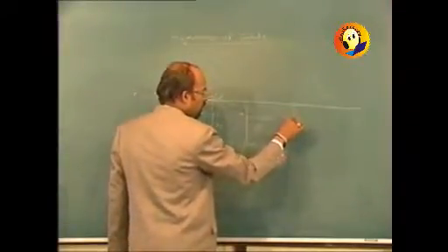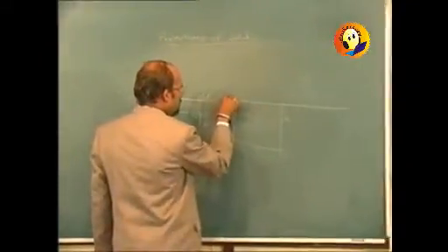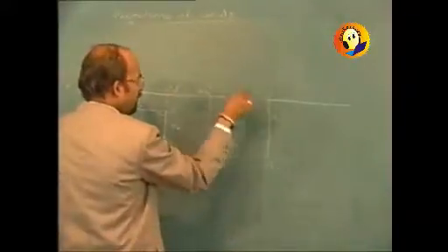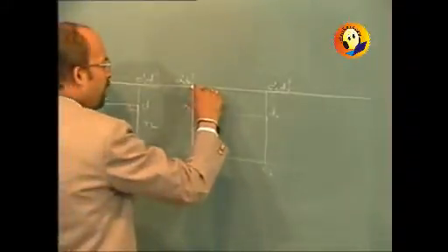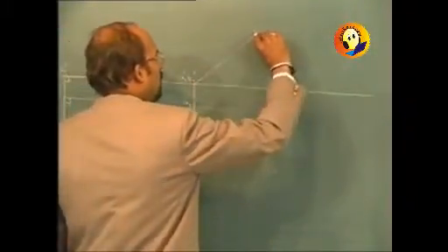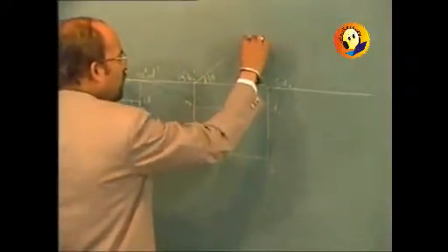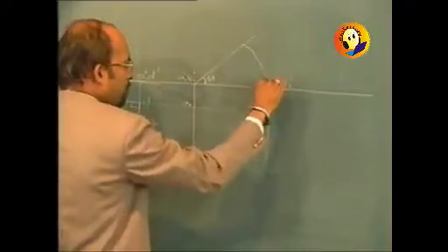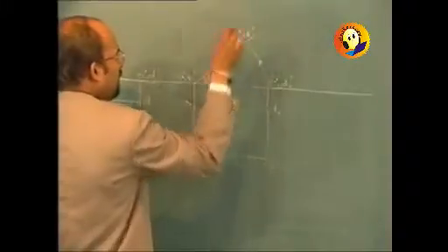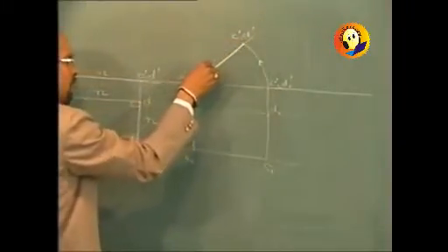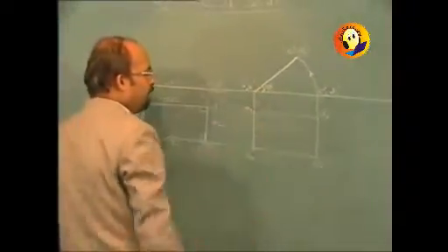now here I will be calling the plan as A1, B1, C1, D1, and obviously the elevation will be A1 dash, B1 dash, C1 dash and D1 dash. And suppose angle made by the plane with horizontal plane is given as some 40 degrees, then this line view gets rotated by 40 degrees, giving us points C dash, D dash being their final position. This will be the final line view, and A dash or A1 dash, B1 dash themselves will become A dash, B dash.